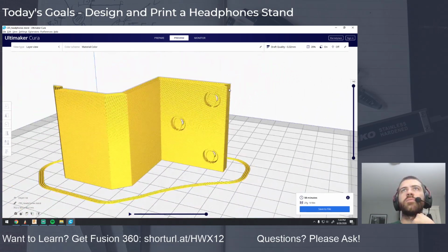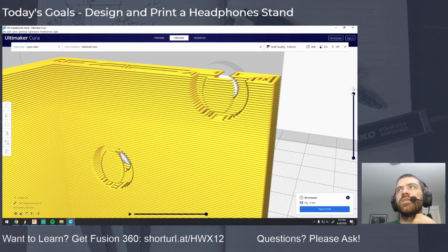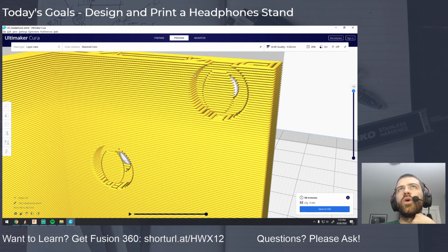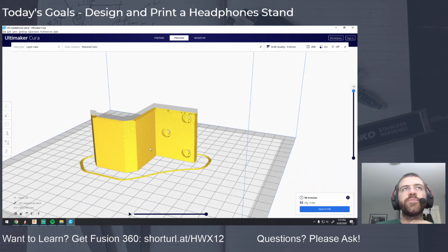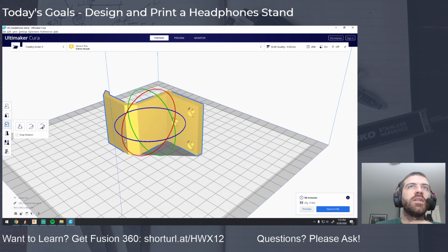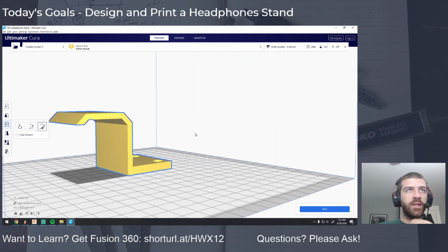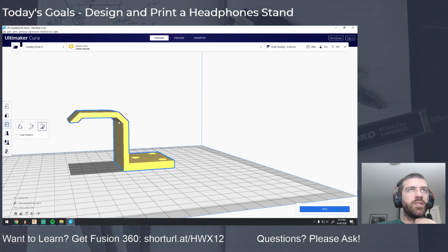The whole purpose of this material is to make sure that when it's printing these overhanging layers, we don't want all this plastic to fall in, because it's basically melted liquid plastic when it prints out. If I had made a poor design choice and had something like this, as this prints up without supports, all this area in here, when it gets up to here, is just going to fall over because it's very molten hot plastic, and you end up with a really bad print.